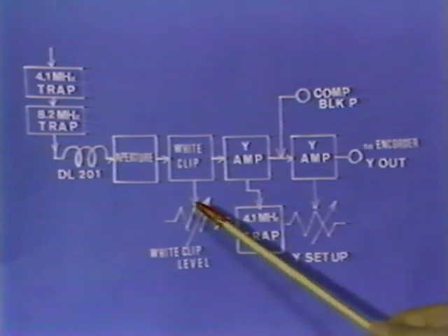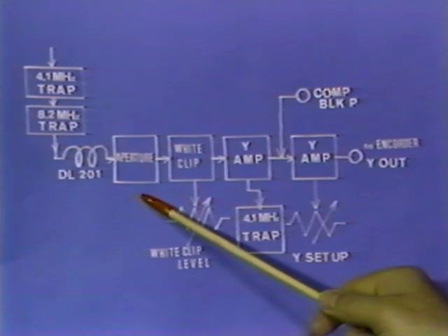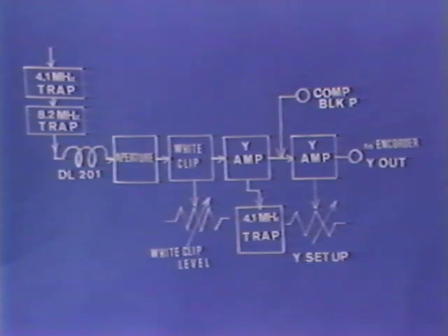Also, to compensate the resolution deterioration caused by the optical frequency component erasing filter, the aperture compensation to enhance the apparent resolution is done. Then, it is to determine the blanking and the setup levels of the luminance signal and to make an output for the encoder. These are the roles of the luminance processor.